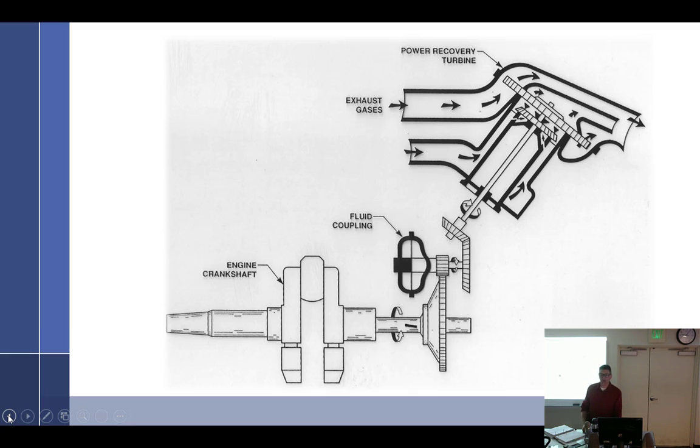Okay, so air is the insulator in a magneto, which keeps the spark going where it's supposed to. You remove the insulator, the spark can go anywhere it wants to, right? So you pressurize it to add the insulation back in to keep the sparks going where they're supposed to go. That's nice. So it's able to fly at higher altitudes if you have that. Yes, otherwise you start getting flashover and they don't work well.